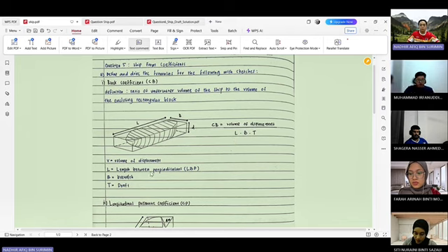The moment is negative 70 times 2.2 and negative 90 times 5.5. The answer is negative 649 tons meter. Next, the ship shifts 100 tons from 3.0 meters to 6.2 meters.